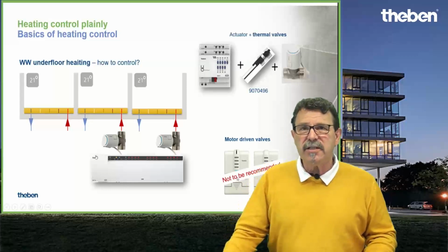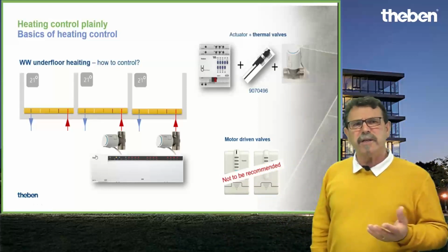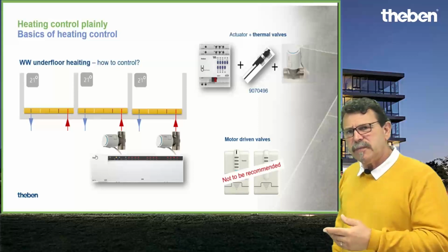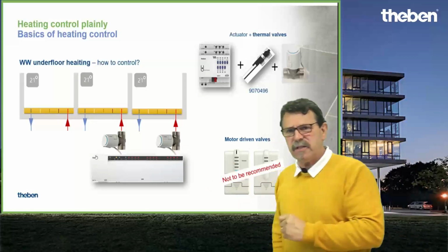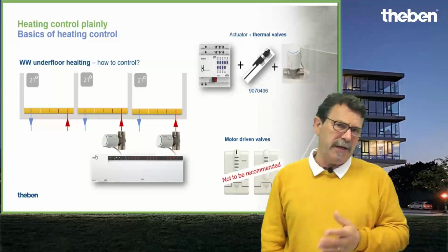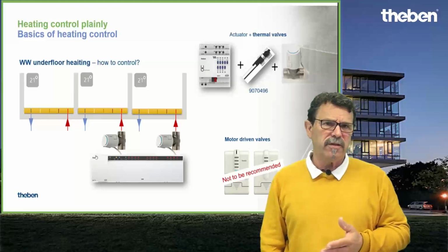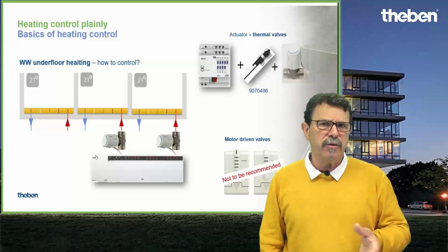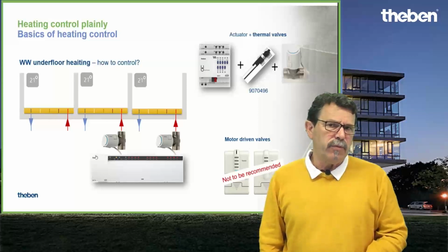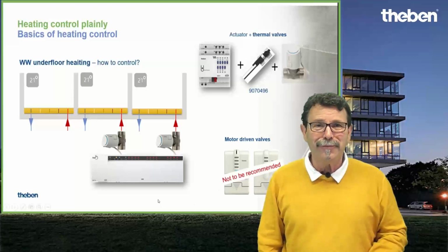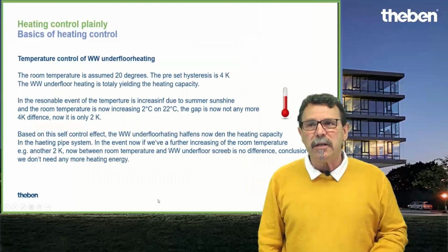In this case, I want to make you acquainted with this: for underfloor heating, as I mentioned, we recommend these thermal valves. Motor-driven valves, okay, the efficiency is not better. That means if you use motor-driven valves for underfloor heating, the underfloor heating is not more precise in comparison to a thermal valve. That's just a matter of price. Motor-driven valves are more expensive. If you want to invest, always welcome. But if you invest, then invest in our Theben motor-driven valves, and then you will have the reasonable result.